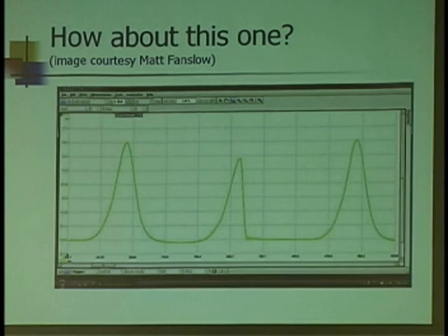But when he tested the cylinder with the in-cylinder pressure transducer, it looked normal. Compression pressure was normal. The pattern was normal. So he went to the next one in firing order, the high one. And this is what he found. When that engine was cranking, for that one moment in time, there were effectively two cylinders on compression. And that gave that slightly higher peak in current draw.